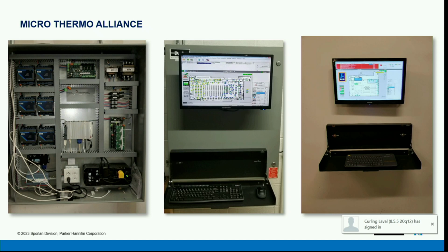So with this node here, with the MT700 nodes I'll talk about, where you can have up to 11 of them all in a train together, all you have to do is press that one button, and it automatically is going to talk to the data logger, and it's going to say, oh, you're the gas cooler node. Here's all your attributes. Here's all your set points. Here's all of your configuration parameters. It's going to download it automatically. You don't have to type it. You don't have to do any dip switches.